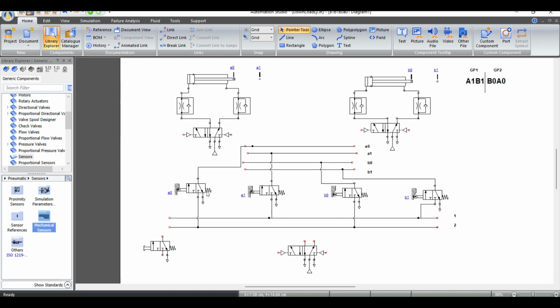After that, the group changing valve contains two ports. One has to be connected to link 1 and the other to link 2. Currently we are having air in link 1, and in the sequence also group 1 comes first and then group 2. That connection we will make. After that, the push button is given to the 5x2 DCV first. This ensures that the piston extends to A1. It touches A1, so A1 is currently having air. So the A1 part is done.